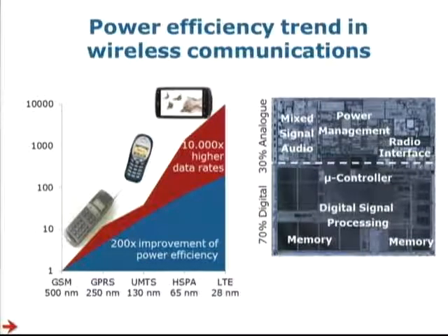Let's go to this one here, the blue one at the bottom. That is the technology deliverables. We see that starting at the early days of GSM and now approaching towards LTE, we have, due to technology, about a factor of 200 of improvement of power consumption and power efficiency. So the remaining factor of 10 for the future seems to be hopefully achievable.